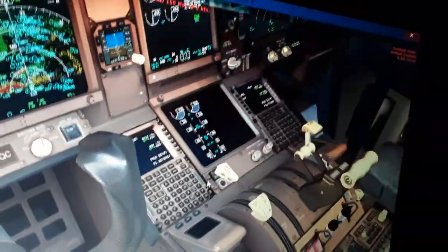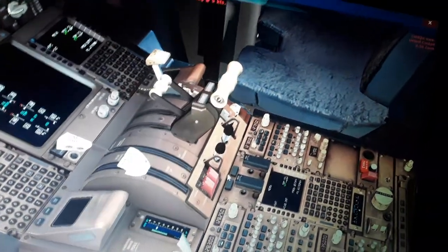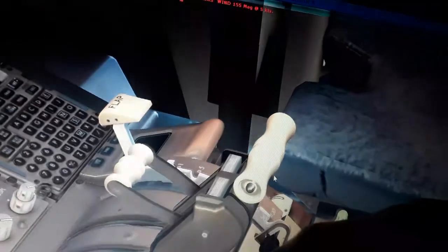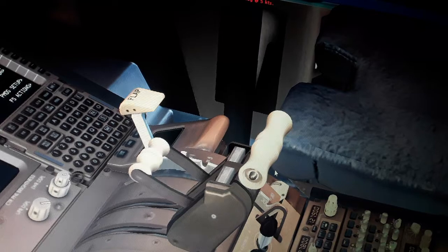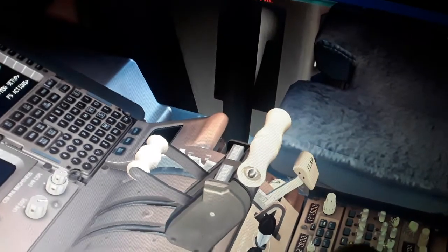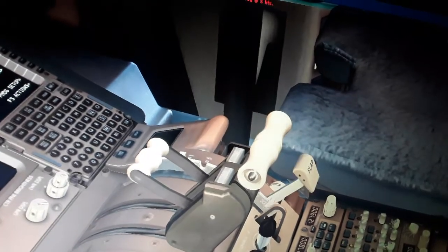So this is the flight management computer also. You can see I can decrease the engine thrust. This is the fuel flow to the engine. You can see here is the flaps position. This is related. This increases the surface area of the wing, so you can extend the flaps and retract them like that. Extend them fully. Also the speed brakes over here. You can see the speed brake message.